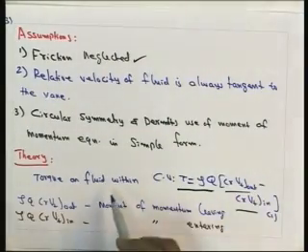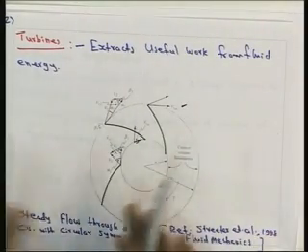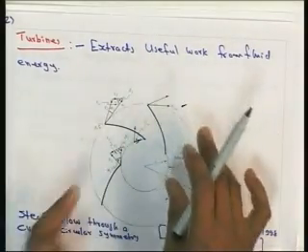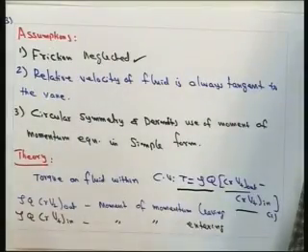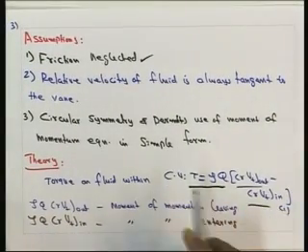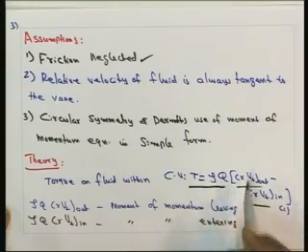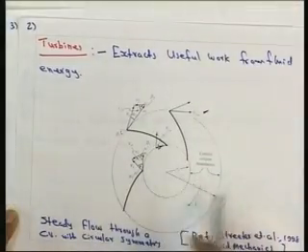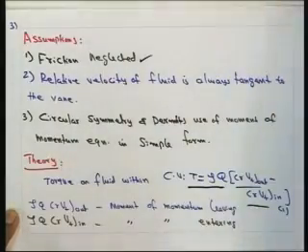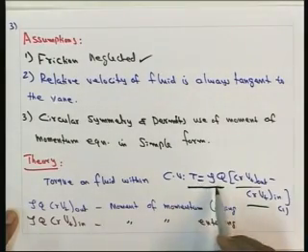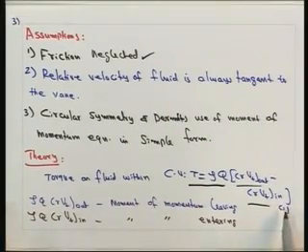Now you can see that when the turbine is rotating, this entire boundary, the control volume, will be filled with fluid, and it is rotating. So, the torque on the fluid within the control volume which we consider is T equal to rho Q r into Vt out minus r into Vt in, where rho is the mass density, Q is the discharge, and r is either R1 or R2, the radius to the external or internal boundary which we consider.